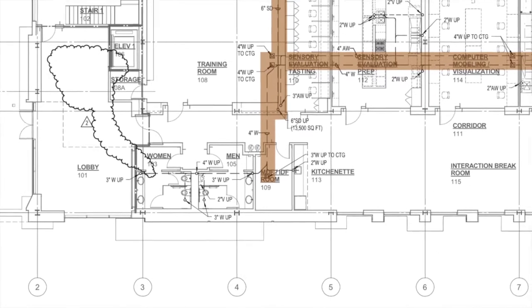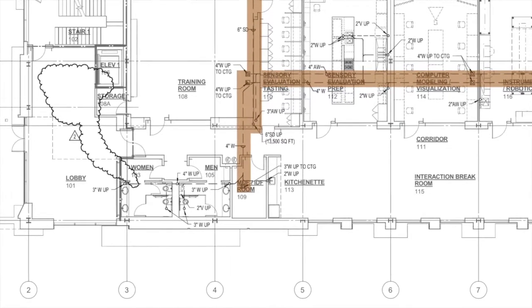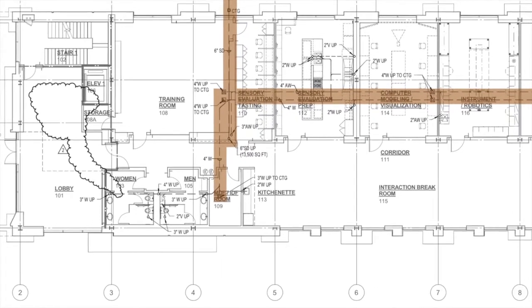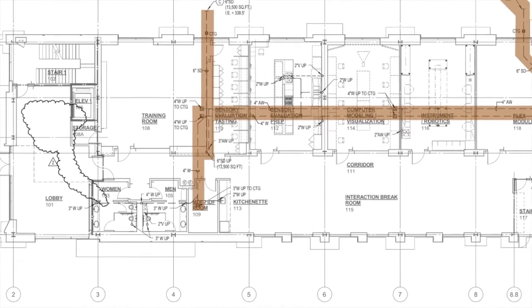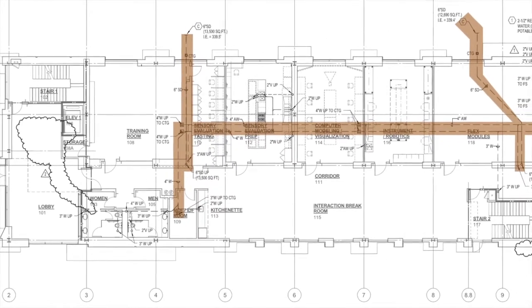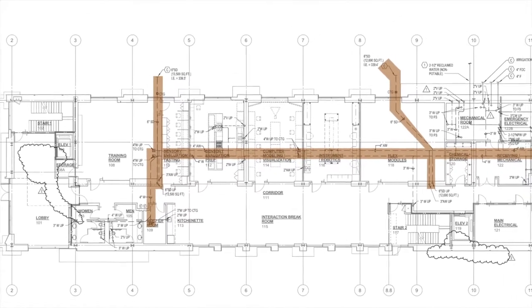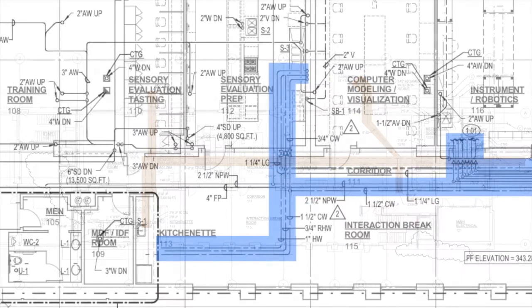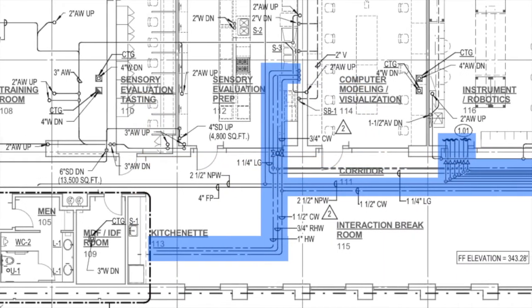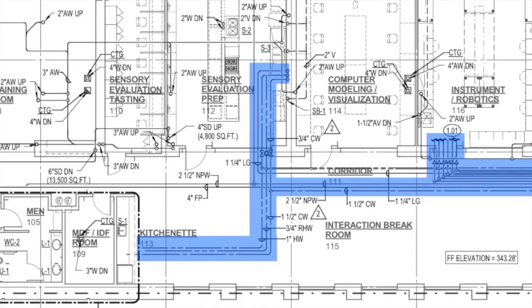Underground piping necessary for the successive floors has been highlighted in brown. Most of this pipe is waste and acid waste piping. It has been grouped into one summation of linear footage in the waste category. This piping is placed before the concrete slab is poured. The exposed piping must be protected and inspected before and after pouring.